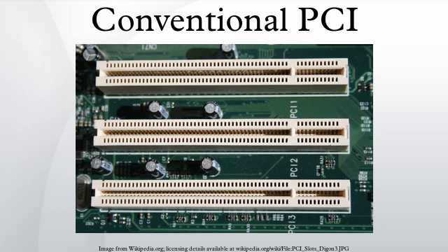Low-profile cards: low-profile PCI cards are defined by a bracket reduced in height to 79.2 mm. The low-profile specification assumes a 3.3-volt PCI slot. The retention screw has also been moved 1.35 mm closer to the fold in the bracket. The low-profile card itself has a maximum height of 64.41 mm including the edge connector.